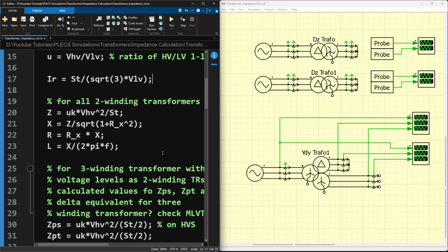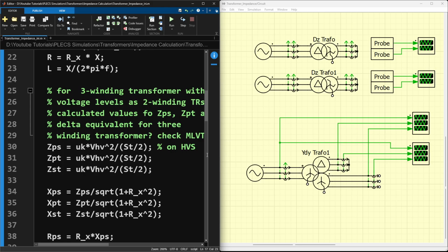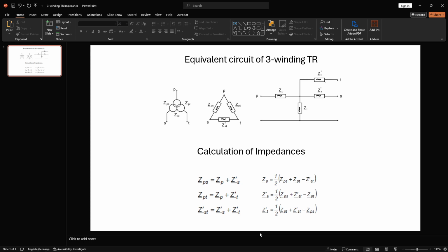So for the three-winding transformer, we still consider the power of the transformer to be the same. And another important point that I need to mention here is that if we consider primary and secondary, you see the flow of the power is not exactly equal to the whole transformer power. In many instances, in real applications, it should be specified. Maybe it's 1/3 of the power, depending on voltage levels on the secondary and tertiary sides. Could be the 50-50 division of the power.